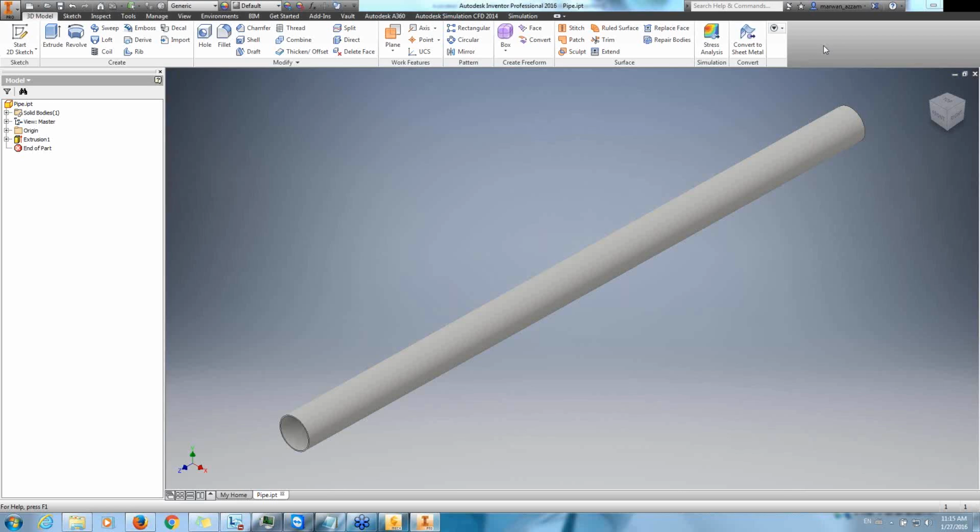It's basically due to the geometry lending itself to buckling based on a load that's not going to cause very high stresses typically, and it's just going to buckle. When we do nonlinear buckling, you might see larger deformations, yielding that is going to lead up to buckling. Just a couple of points that came to mind when Dean was going through the slides and the bullets here.